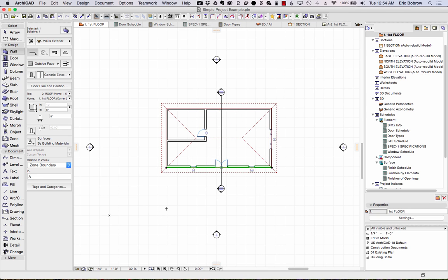So how do you add this in to your model? How do you add it in to your environment so you can create a report that includes walls, floors, roofs, and other construction elements beyond the ones that are provided in the library, like doors, windows, and objects? So to extend ArchiCAD's capability to hold on to data and use it for things like drawing notes as well as specifications reports, we're going to work with something called IFC fields.